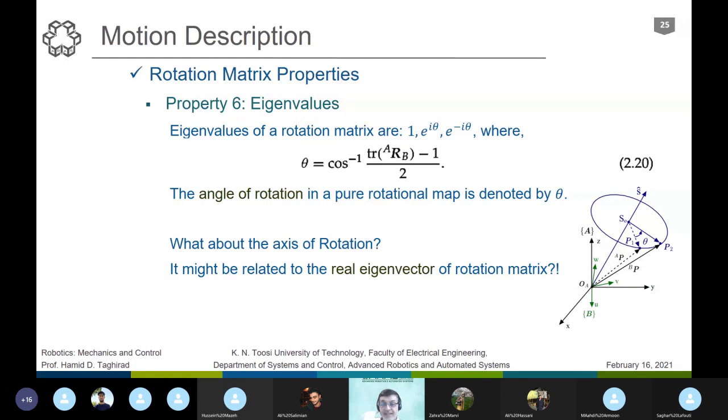But, Ali John, the important thing is the angle of rotation and the vector of rotation, which we call a screw axis. These are inherent to the motion. This doesn't change. Many things will change, almost everything. But the inherent quantities, which are embedded in the system, this angle and this vector, the angle of rotation and the vector of rotation, don't change.